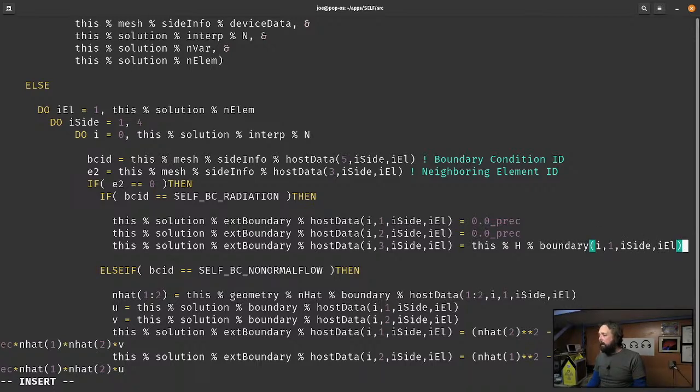Okay. Whoops. What I need to remember is, the way the mapped data class works is you have interior points, those internal quadrature points to an element. You have boundary points for your quadrature element, so you can index over the edges. You also have this extboundary, so it's a way to impose an external boundary condition or an external state that you want to use.